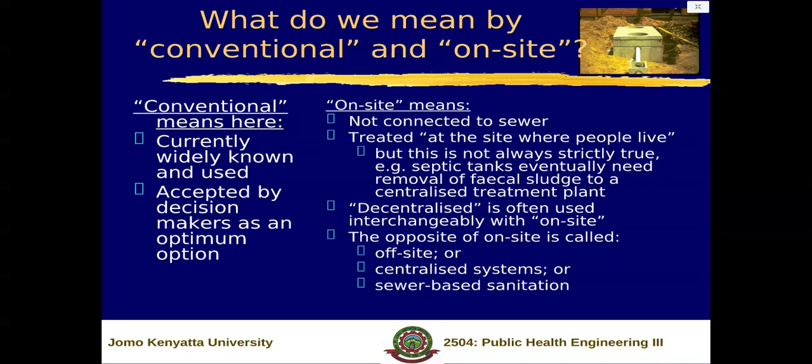Therefore, if you see somebody trying to design a septic tank to hold water for months, that's a problem, because we only hold the solids, not the water. And therefore, most on-site treatment systems will include a septic tank as a primary settling tank.